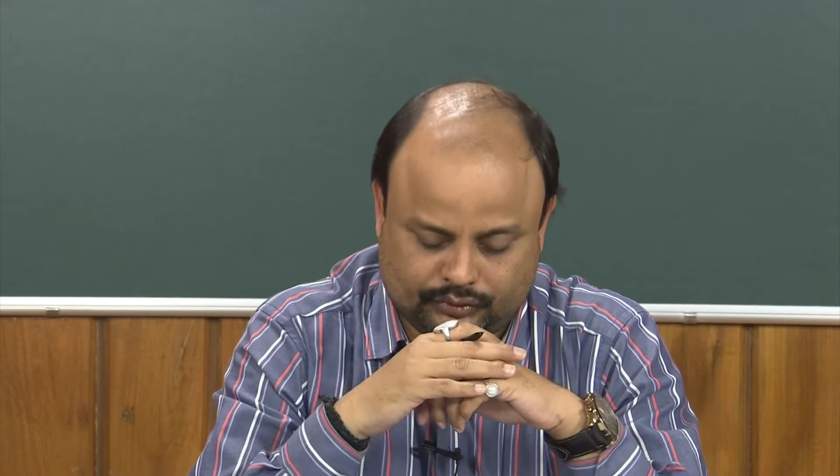Okay. So, that is the major boost in gamma ray tomography or X-ray tomography. The system diameter is not a limiting factor. You can increase the diameter of the system. Only what you need to do is increase the source strength, and that is in your hand. You can use higher activity of the source.